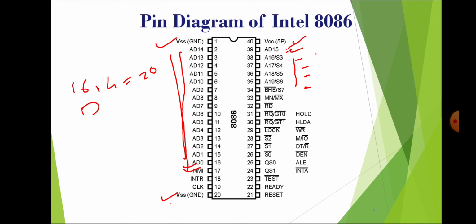So what is meant by this non-maskable interrupt? This is an edge triggered input which results in a type 2 interrupt. When programming comes into the picture, then you will understand exactly what an interrupt is. Suppose during execution of the program an interrupt arrives. Interrupt means some problem is there, so this bit will get high. A subroutine is then vectored through the interrupt vector lookup table which is located in the system memory.